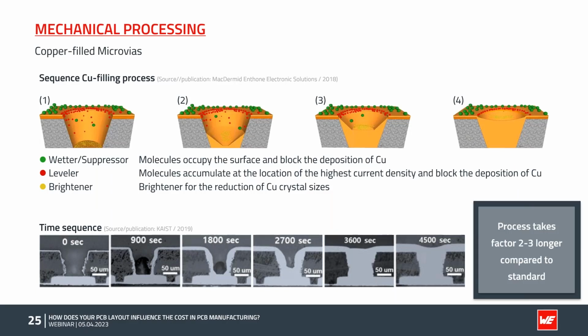And we have quite a lot of applications, even in the automotive area, truck gearboxes, for example, which have run for 20 years out there on the market without any defect, where we didn't copper fill the microvias. The customer has small voids in his balls, but it's all tolerable and still pretty reliable in that case.